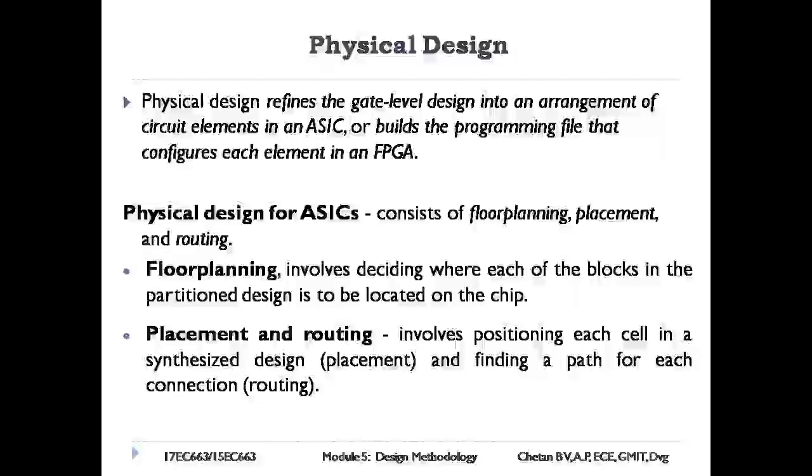Number 3, the blocks should be arranged to make the chip as close to square as possible, since that influences the size of the package that can be used. Square chips are easier to package than rectangular chips. Floor planning also involves arrangement of power supply and ground pins and internal connections.